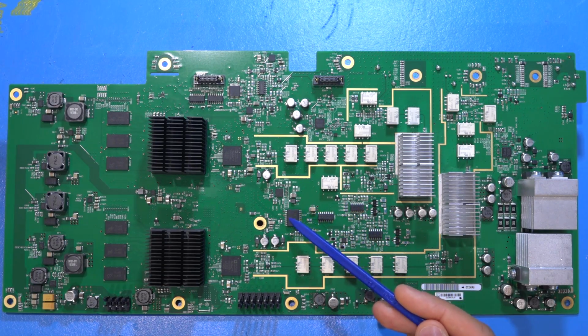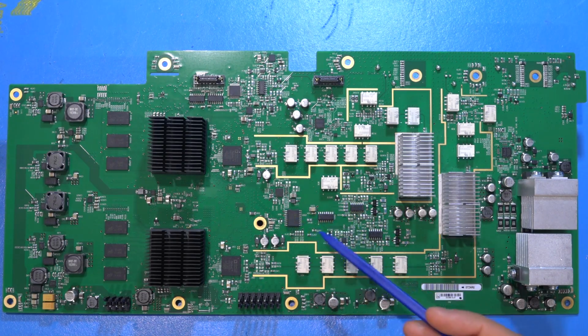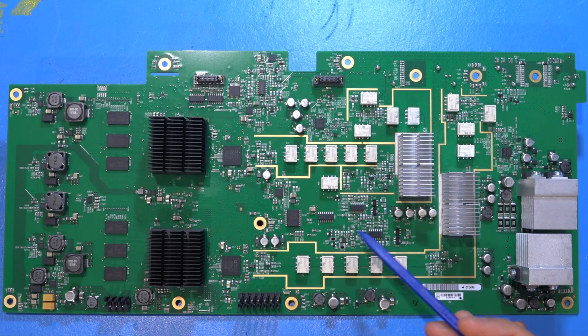So whenever you see a single output DAC and an analog mux and some op amps and so on, you potentially have some kind of sample and hold circuitry where you store the value and then mux it through 8 different channels. That's potentially one way that it is being used, and this can be used to apply offsets and trimming and so on, and potentially get good THD performance from the output drivers through this common section.